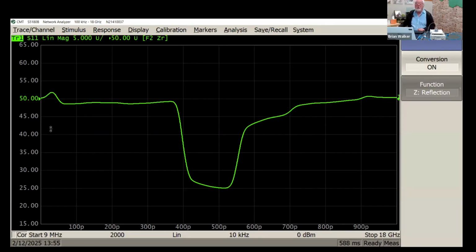But of course, the shadowing of the 25 ohm section is causing us to have some error here on the right-hand side. What's this little bump on the left-hand side? That's the connector. You should be used to that. And the impedance is a little high, indicating that it could use a little more capacitance to ground. And we could probably do something to improve that. You could get in there with an X-Acto blade and try to fix that, or some copper tape if you're a real hands-on person, or you could turn right to an electromagnetic solver and try to fix it. So this shows us the time domain measurement that we just made on this board.